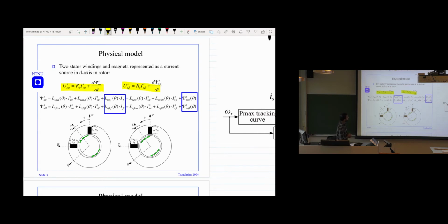Those are for the stator voltage. And now in the rotor we have a permanent magnet. When it's a permanent magnet, we are assuming that it has a constant field current. So the field is shorted. This means there's no voltage equation for the field, only the armature, only the stator voltage equation that you have.